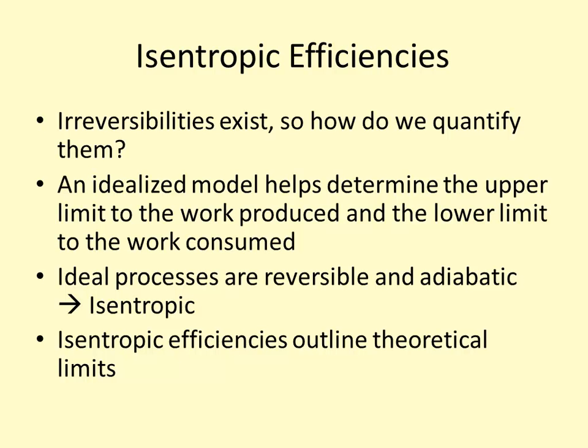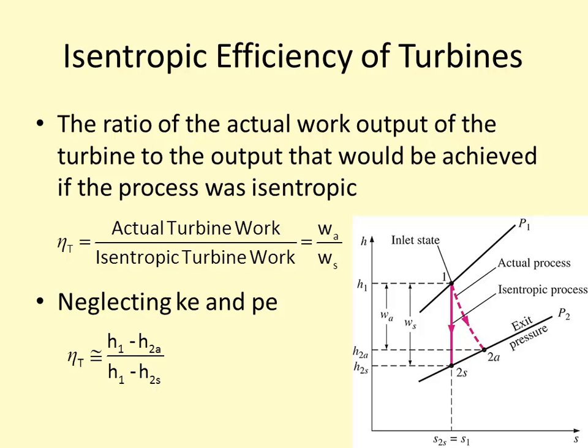The important thing to remember is that even though a compressor has an isentropic efficiency that's based on the reversible adiabatic case, a compressor can do better by adding cooling to the process. But that's something that we have to do. It's like an outside process that we add to our system. Okay. But the isentropic case, again, identifies the limits for a theoretical work.